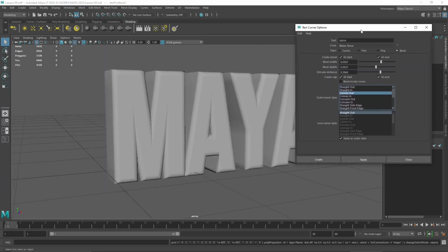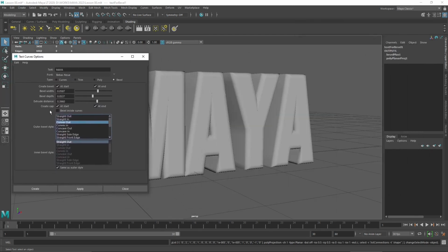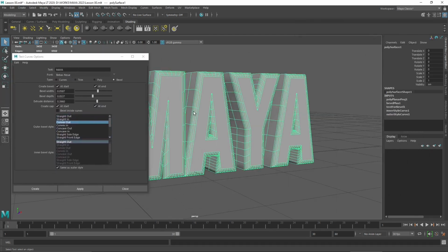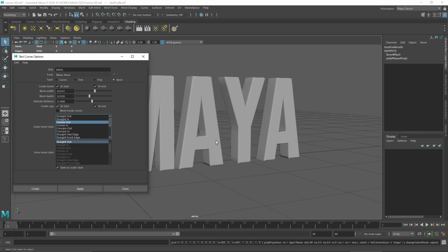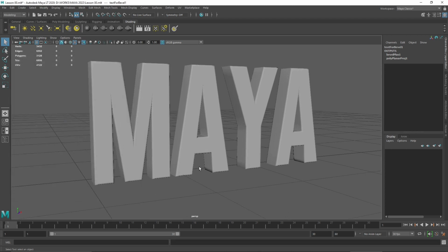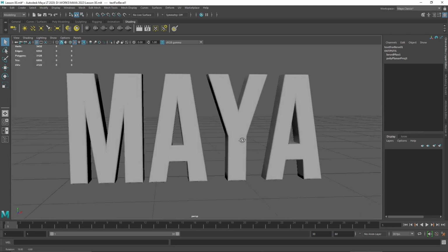Yeah, looks better, but maybe I want to do something different. So I get back here and change. Well, I can select it with the left mouse, and then delete, and then I can move around here a little bit with these parameters and recreate it again. Now this is basically parametric modeling, when we model by setting parameters. This is another type of modeling that we usually have in any software. Okay, now it looks fine to me, so I'm gonna close this, and there's my first object, my first text.